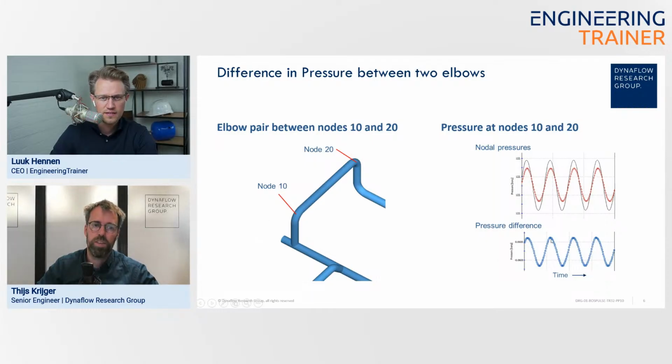So if this is the result of the pressure difference, then also the force will show the same profile, and it's oscillating around zero, positive and negative direction. So it isn't like those other graphs where we saw those positive pressure pulses in the system. It's not like a short hammering in one direction, but it's, as you say, an oscillating wave around zero, the force over time. Yes.